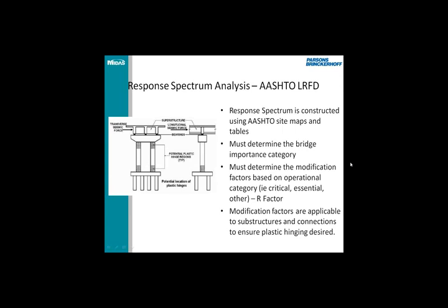So you want to make sure that the plastic hinging takes place, as in this diagram shown, at the top or bottom of your column, and not below grade where it's going to be really tough to get down there and repair your structure.